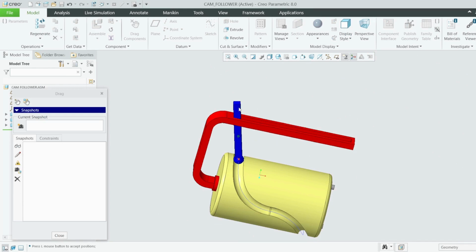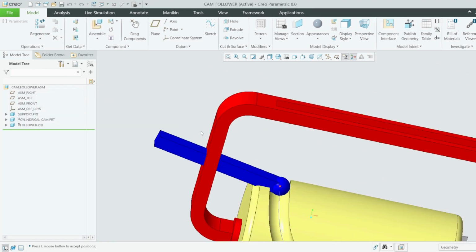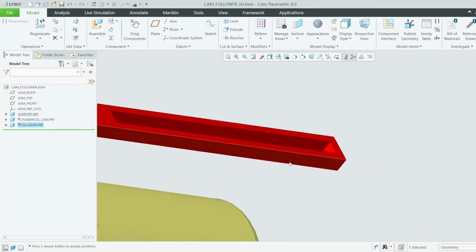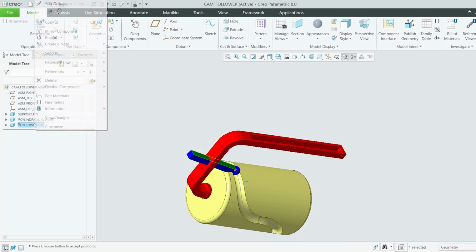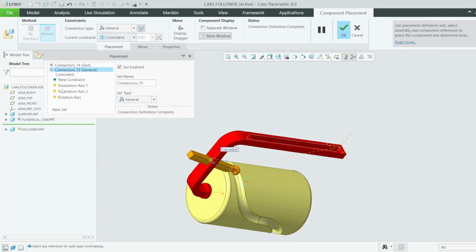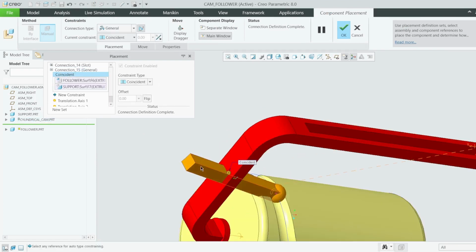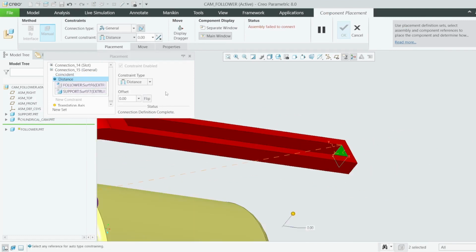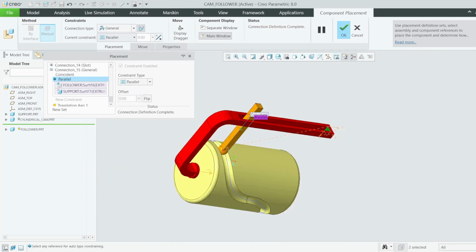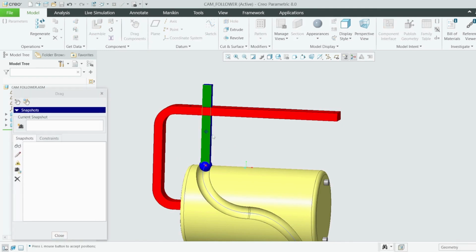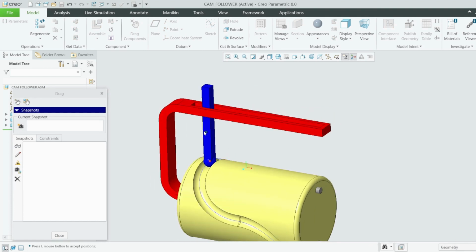Now you can see it is not rotating, but it is moving like this. For us to prevent this movement, what we do is we ensure this surface and this surface remain parallel. Don't make them coincident, otherwise it will not move. Go to this one here. On this here, general, another constraint of this one here to this, but not coincident, we said parallel, like that. You can see it is parallel. If you now try to move this, you can see now it is moving without rotating.